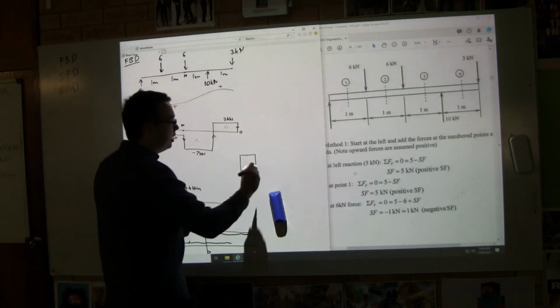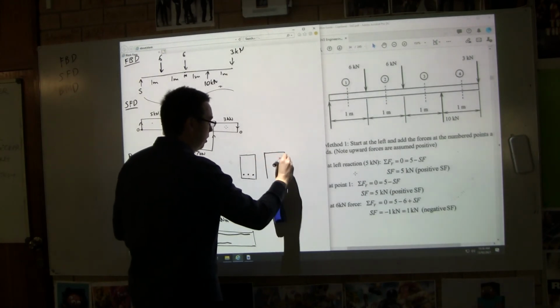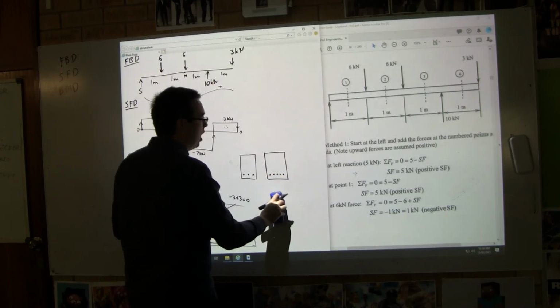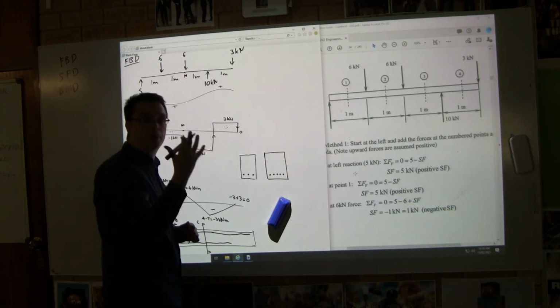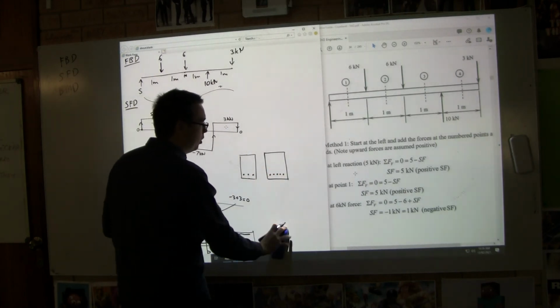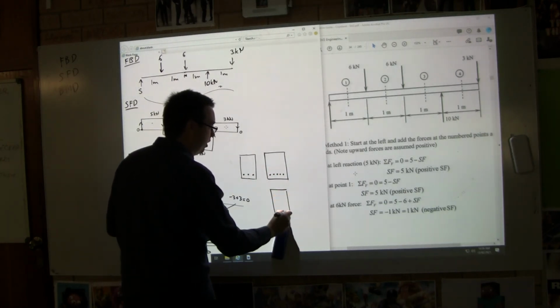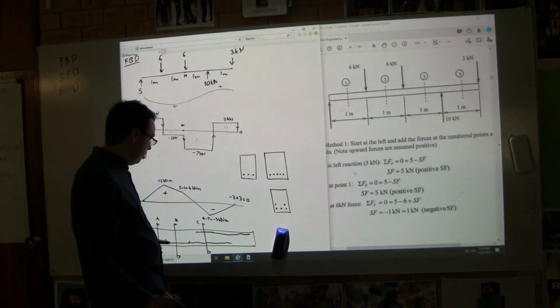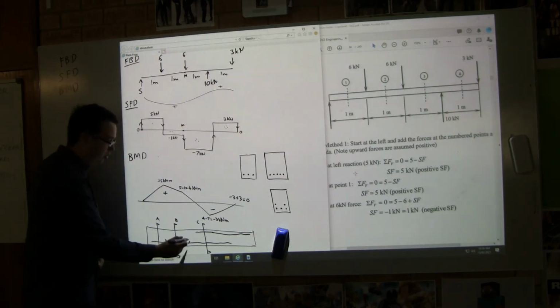And then at the next spot, at B, what we might do is squash in an extra 2 bars. If it gets a bit too squashy, we can go up. So an alternative is we could say, well, that doesn't quite fit. We could go 1, 2, 3, we could go like that. That's an alternative way of laying it out. And that's why sometimes it looks like 2 rows and sometimes it just has these little lines to say, put extra steel there.